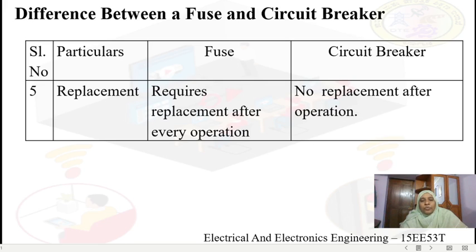In particular, if you want to see the working of the fuse, when the system is healthy, normal current flows through the fuse which is below its melting point. Hence, the fuse element will carry the normal current without overheating. But when the fault occurs, as soon as the high value current flows into the circuit and through the fuse, it gets heated up, which is above its melting point, and it breaks or it melts. So once it melts, it is going to make the circuit into an open circuit. Because of this, a lot of heat is generated. Now this heat will vaporize the fuse element, which is usually made up of silver. The silver will become silver vapors.